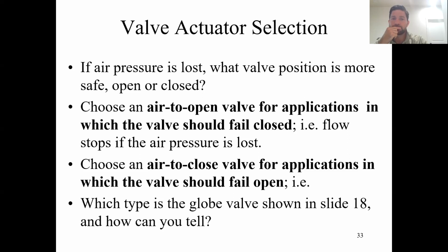Some like dangerous chemicals, hydrocarbons. Sure. If you have a valve that's controlling the flow of a toxic material into a process, you don't want that to be unrestricted into the process. I mean, in general, you might even just say that for a particular reactant going into a process. What's something else? There's something really obvious that you don't want to fail. You want it to fail closed. You don't want it to be left open and uncontrolled.